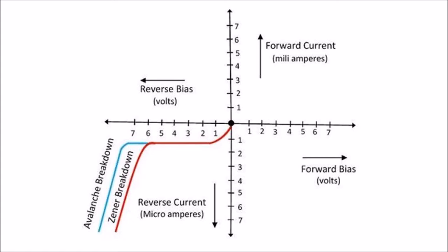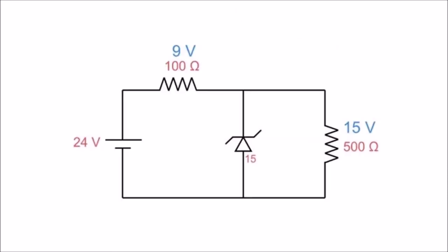The Zener effect has a negative temperature coefficient while the impact effect experiences a positive coefficient. The two temperature effects are almost equal at 5.5 volt and cancel out each other to make the Zener diode rated at around 5.5 volt the most stable over a wide range of temperature conditions.